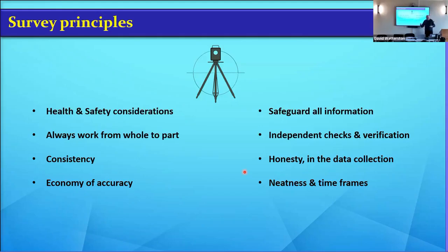by that much. And what you normally do then is average that difference through the amount of change points you have. So you get it down to 1 or 2 mil or nothing. But I've had surveyors who ended up with 30, 40, 50, 60 mil error and would fiddle the last backsight to make sure that it closes. The thing is that you don't know where he dropped it. If he dropped it in the last shot, fine. But if he dropped it in the first shot, that means everything that he's leveled is 50, 60 millimeters out of position. So honesty in data collection is paramount.